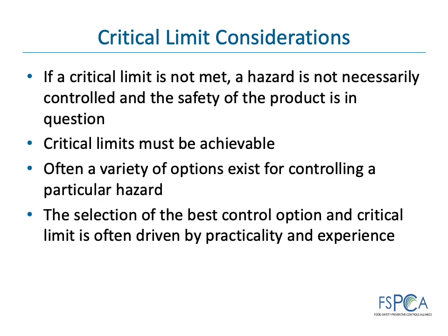For example, processing equipment could not easily maintain the exact value of exactly 160 degrees Fahrenheit or 71 Celsius, so the critical limit would be set at equal to or greater than 160 degrees Fahrenheit or 71 Celsius. This allows the CCP to be achieved and gives the option of exceeding it, say for being more conservative or to operate at a higher processing limit.